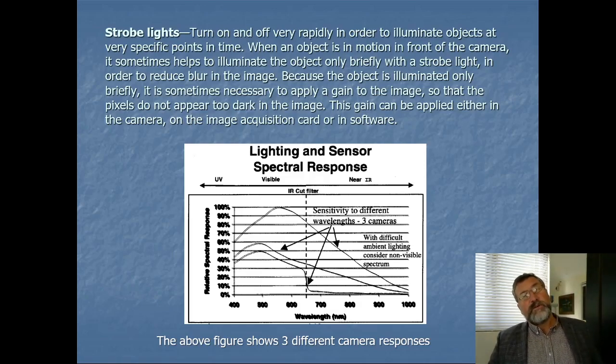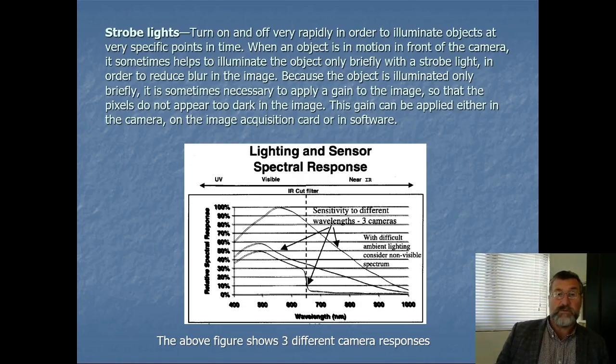This might have been popular years ago, because years ago they used to use TV standards for recovering the images in machine vision. Nowadays, we don't use TV standards for lots of reasons. We get higher resolutions with digital techniques, and we can use any resolution we want and just capture the image when we want to, rather than capture a series of TV kind of images. So nowadays, we'd have the lights on continuously, and we just capture the images when we want to see where the object is. So it's more of a practical approach, really.